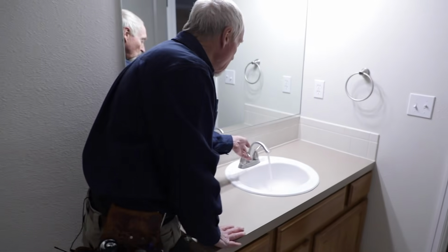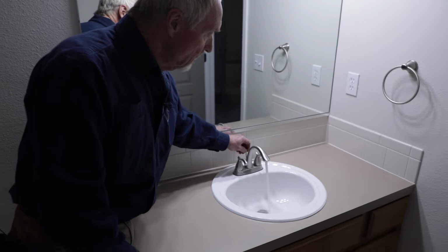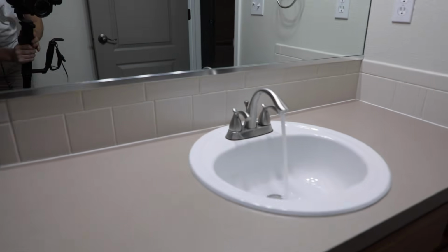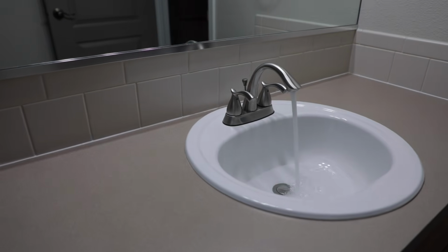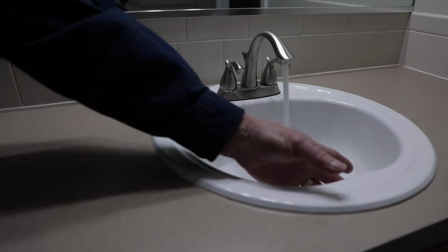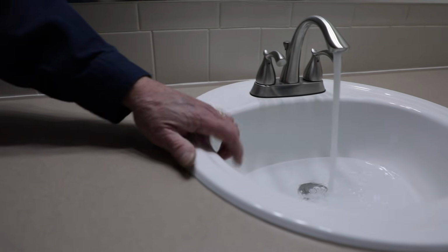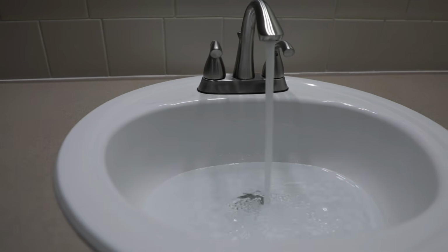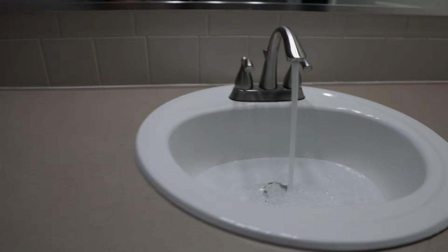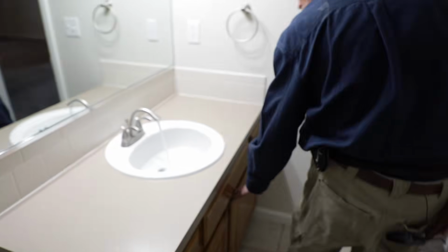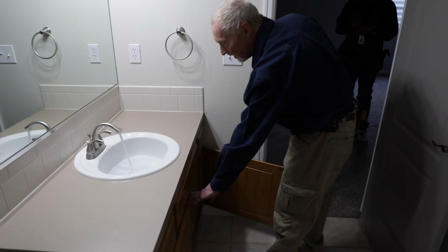So over here with our sink, run some water. I like to close off the stopper if it'll close off. I like to add some water to the sink. I'll fill it to the overflow holes. In this case, this is a steel sink. Steel sinks typically are a little more vulnerable to having problems underneath than ceramic sinks. So I'll run some water in here while that's filling.